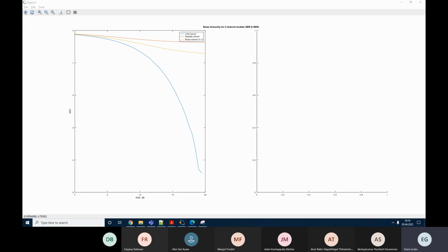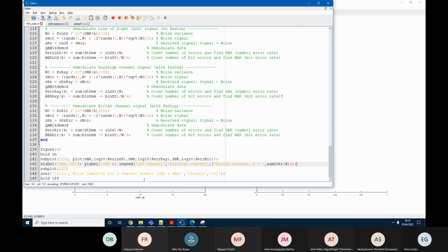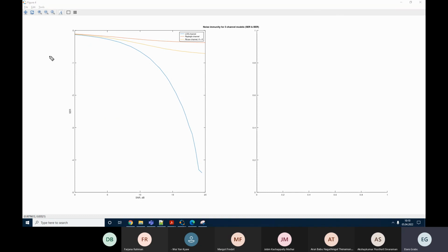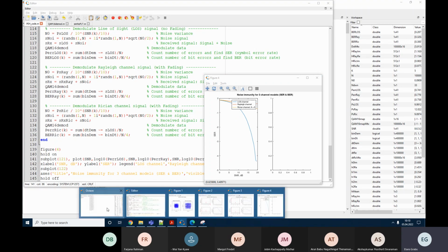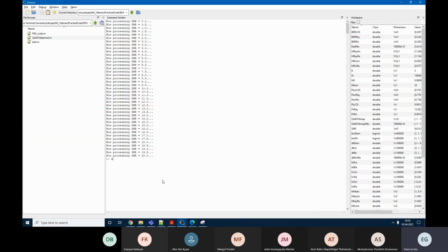Well, actually, I also want to add some grid lines to this plot. Grid on. And maybe we can place this legend into some better position, because here we have plot, and if we don't really maximize the window, this legend actually is on top of our lines, which is not nice. It would be much nicer if we could move this legend here, for example, right? So let's see help on the legend command. Help legend, how it could be done.